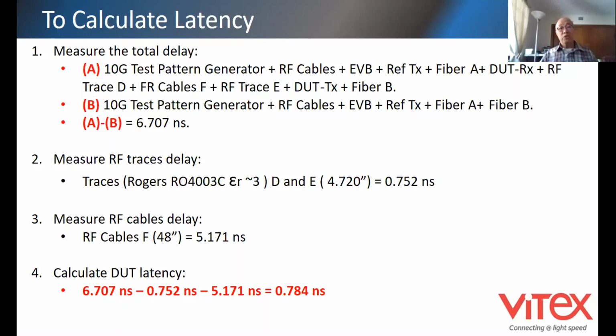Everything is manual, right? Analog, by hand. The one I mentioned is the specific pattern you might want to generate. For instance, you might want to program a bit like a 1 and then 0, a bunch of 0s, and then 1, 1, 1, to identify your leading bit, so you can locate the bits to count with reference to delay. So sometimes you can use pseudo-random, because the pseudo-random patterns do kind of repeat in a way, so you get confused which bit to count. But sometimes you can count it if you do it carefully.